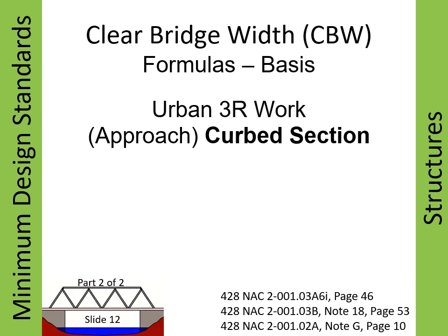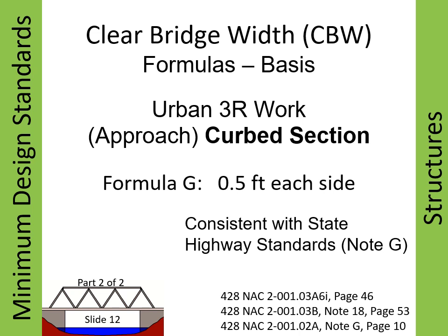For 3R work done under urban area standards, the Board of Public Roads decided to use 1/2 foot as a minimum clearance from the edge of traveled way to the nearest vertical roadside element on a structure. This is consistent with State Highway Standards Note G on page 10.